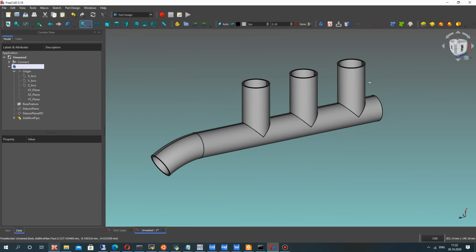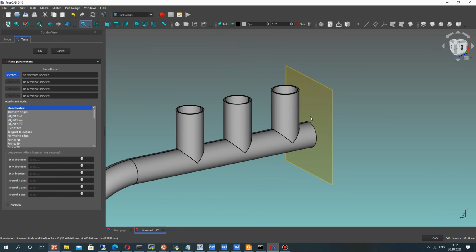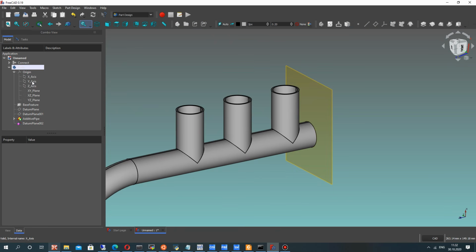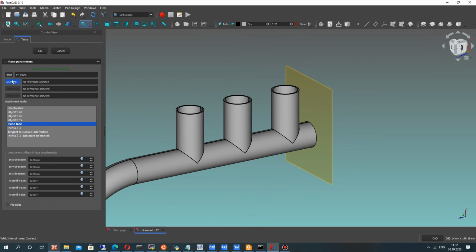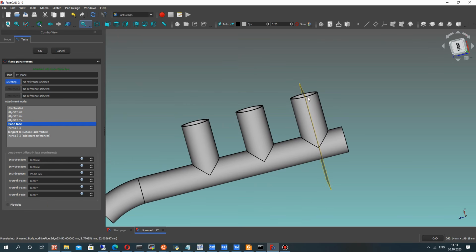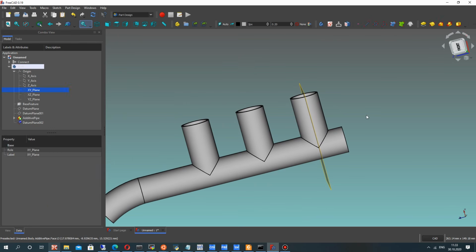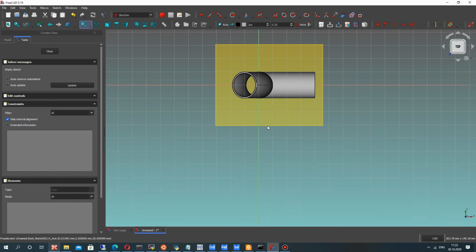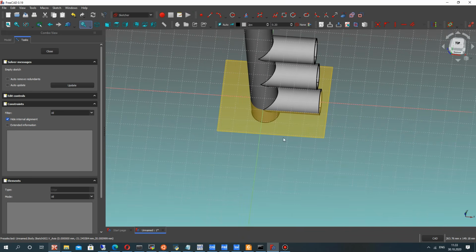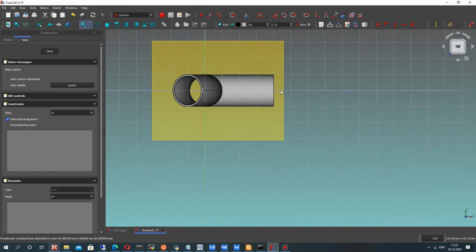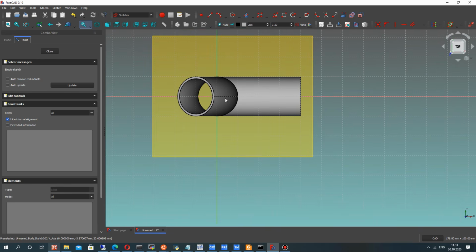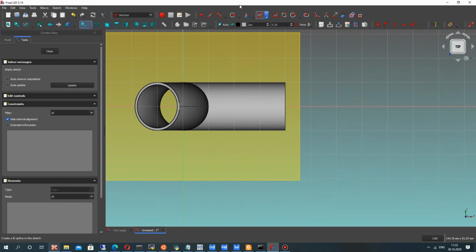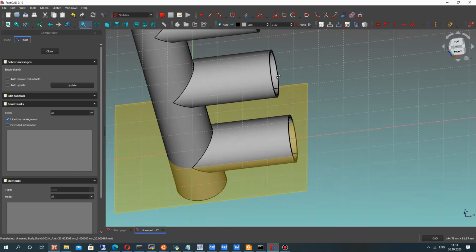It looks good. So in the next step, let's continue to create this algorithm, create the plane, choose this XY plane, and change the position of the datum plane. We have to translate our datum plane here. It is half of the pipe of the manifold. Okay, let's create the sketch for this datum plane and choose the top in the cube, and we have to create the elbow.